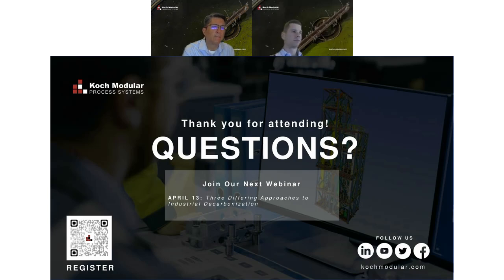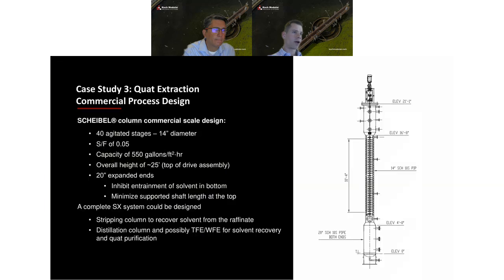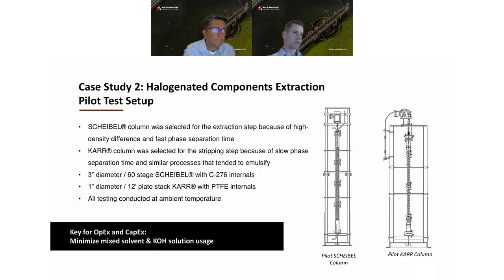Okay, thank you. Another question is, what do you recommend for recovery of the solvent which dissolved in the feed? So for example, the MIBK solubility in water is 1.7. There's a lot to lose per batch. So to recover the MIBK, it would be, typically speaking, a process kind of like this.